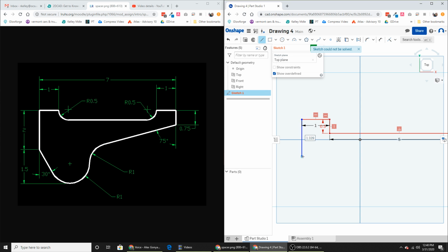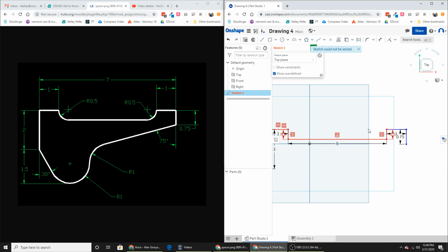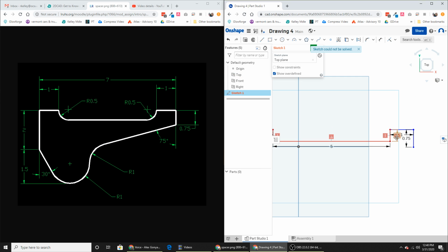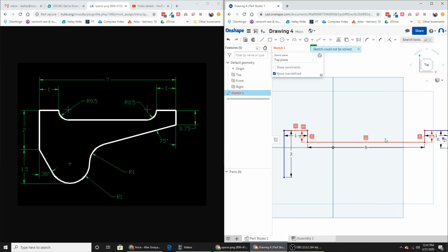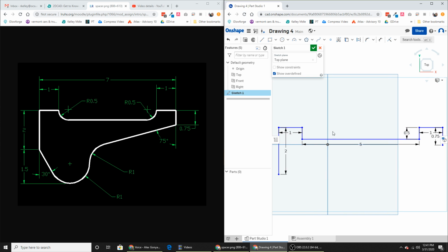and down 2. Alright, now I'm going to just click the sketch here, or the line tool, to turn off my line tool and see exactly where the problem is. It doesn't like these 2.5s, so I'm just going to delete that one. And now it's happy. And the reason it's happy is because it's already got 1 over here, and it really doesn't like to see features duplicated.